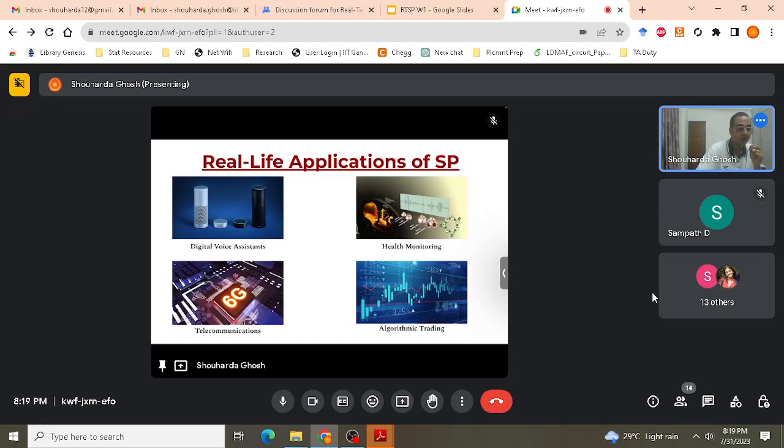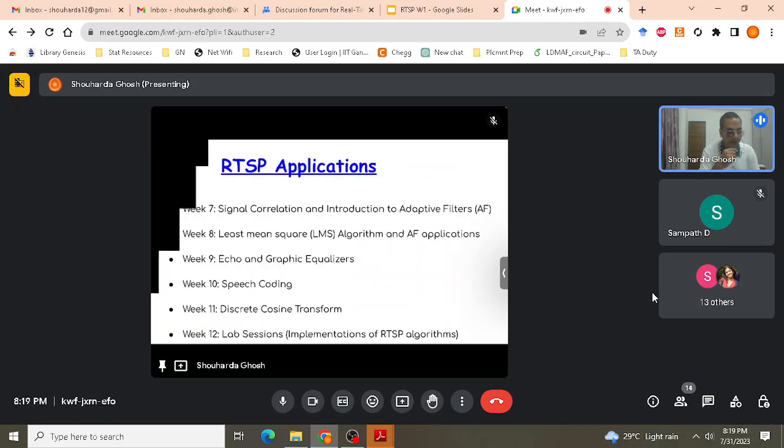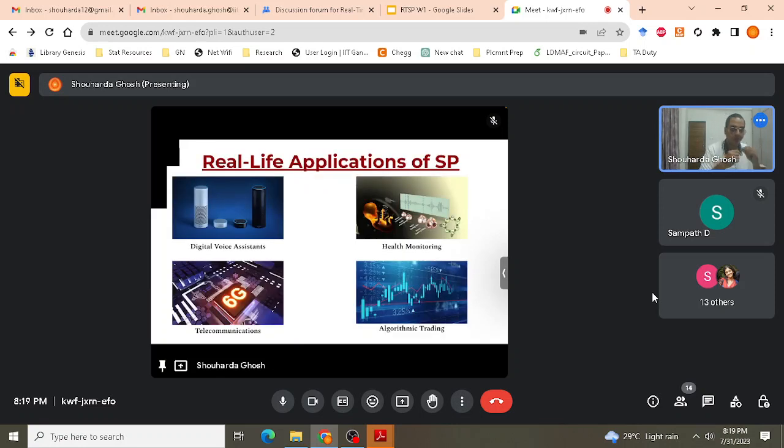Now if you try to directly put one sensor on it, what will happen is I will not be able to get a proper signal. I will make some kind of misdiagnosis. So what is the solution? We mentioned in our previous slide adaptive filters. So what we do is use an adaptive filter in which on one side we take the mother's heartbeat signal, one sensor for the mother's heartbeat signal, and another sensor which goes to the fetus. So we acquire the mother's signal and cancel it from the signal we are receiving from the fetus's heart, and at the end you cancel the interference and obtain the desired signal. But it's not that easy.